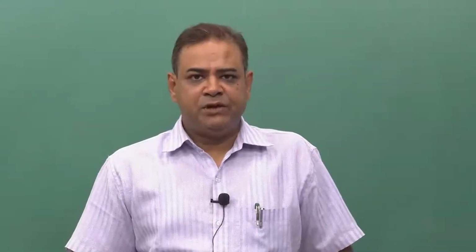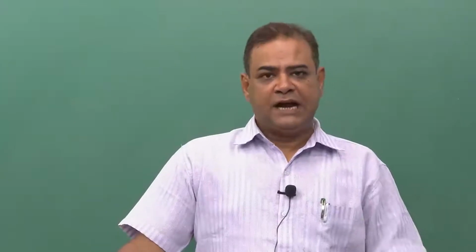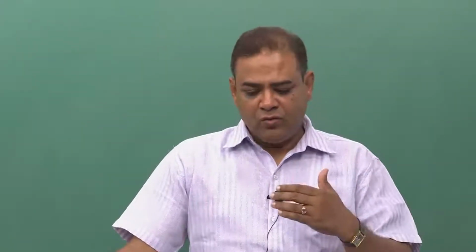In our last lecture, we ended at the JMA equation, and we have also seen how x varies with time at different temperatures, at a particular temperature below the equilibrium transformation temperature. Now, we would like to see how the TTT diagram is plotted from those x versus time plots at different temperatures. And remember, we are in the regime of isothermal transformation.